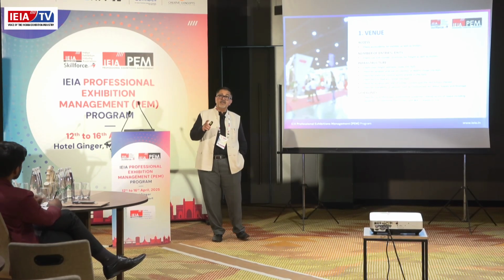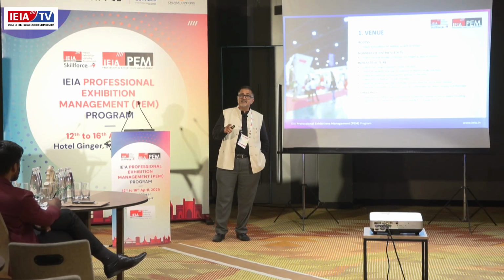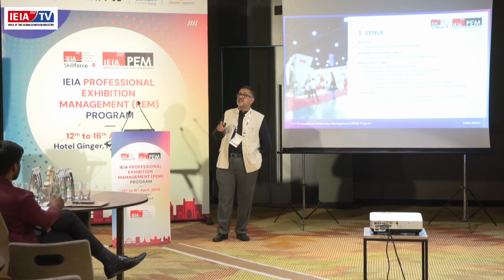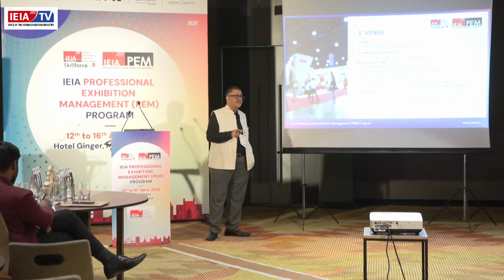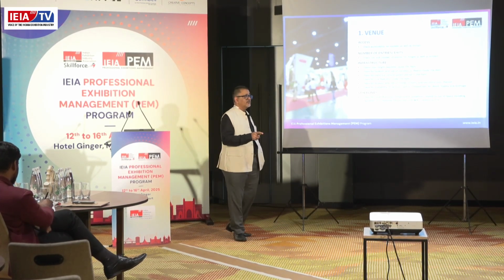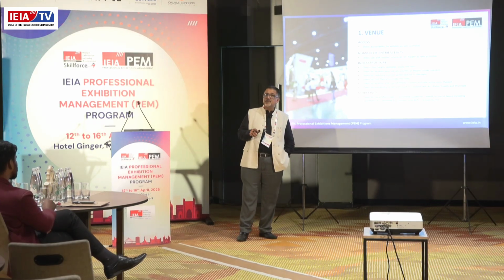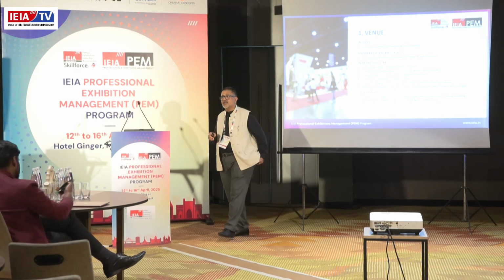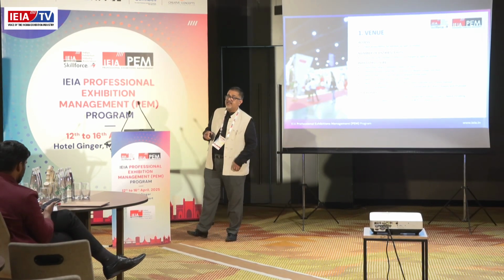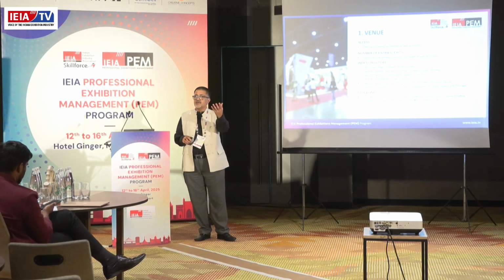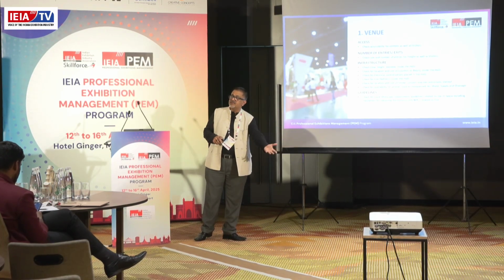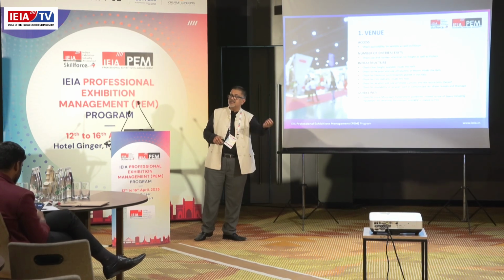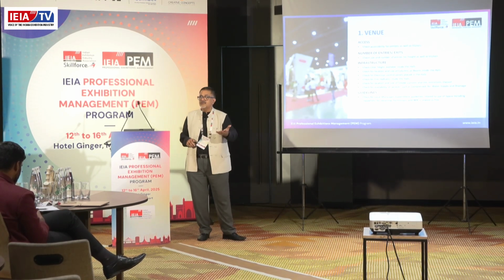It's also important to mark the services that are there in the trenches under the floor, because you may have to tap some services from the floor through the trenches. If you don't have your trenches marked out on your layout, you may find that the point where you want to take the services out is where the exhibitor's conference room or his president's room is, and he will not allow you to do it.